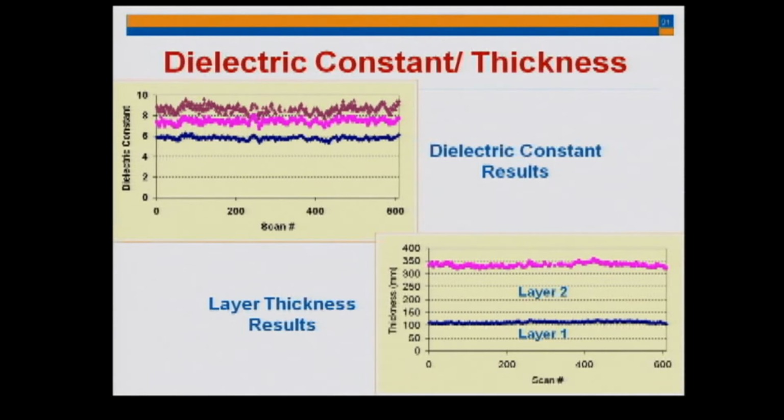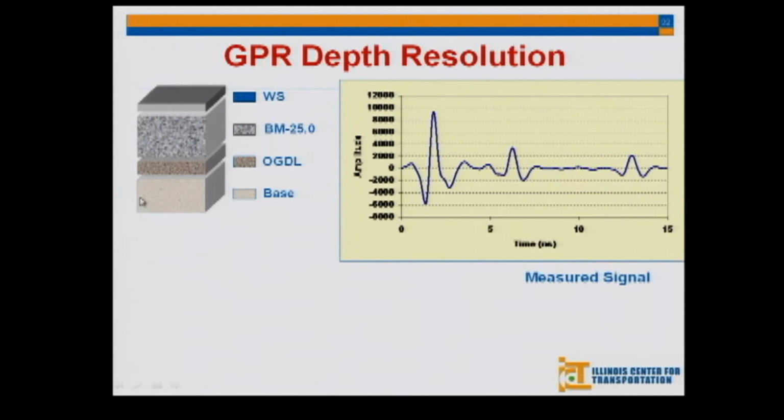The difference here is the thickness that I come up with for my pavement. It's based on the actual dielectric constant for each point we are measuring, so it's not an assumed value. The problem in the current GPR system is you always assume a value, or you calculate the value from the surface reflection and use it, and that will lead to some cumulative errors, in my opinion.